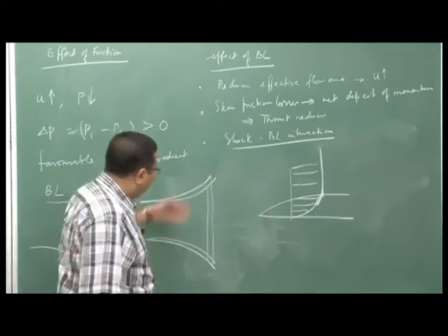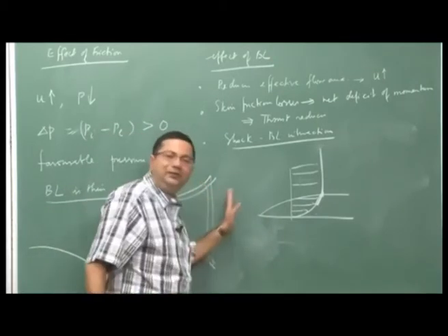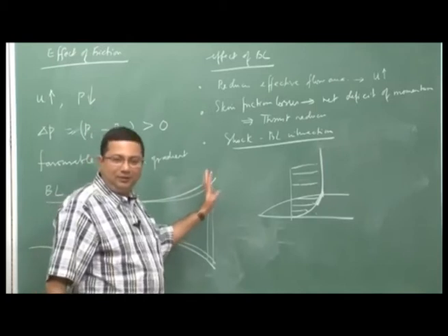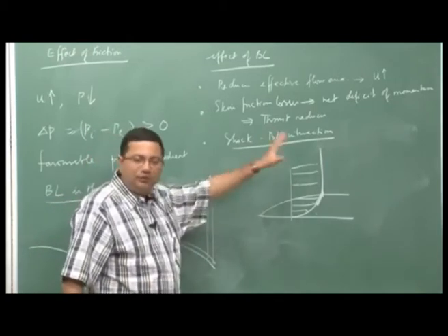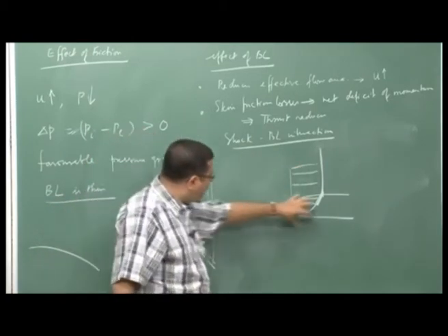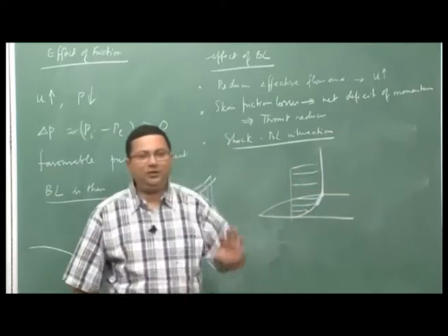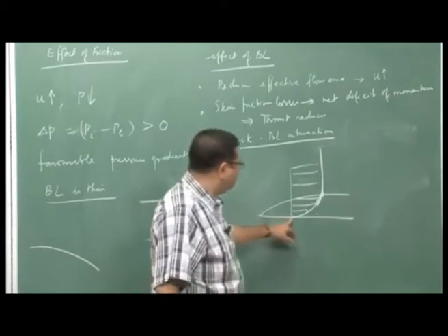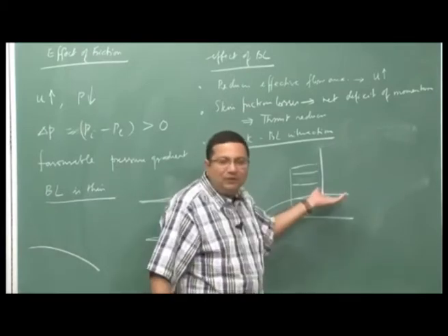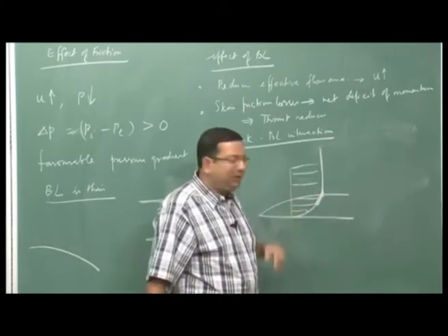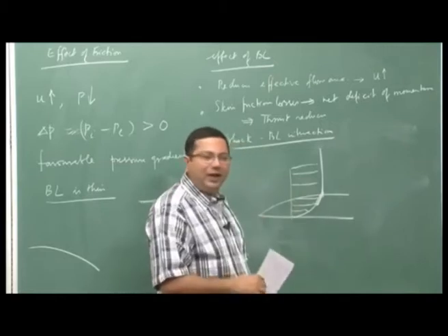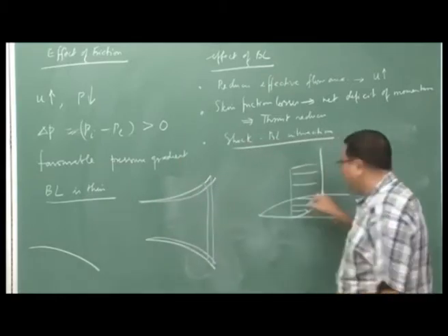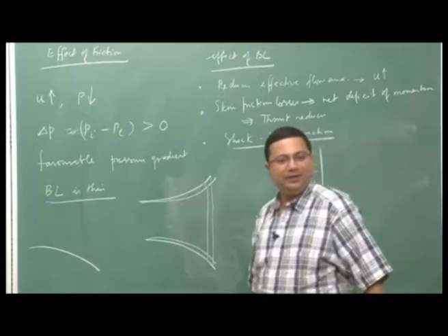So, even if there is no shock wave entering from the outside, or because of the condition of the overexpansion, there will be a shock wave close to the boundary layer, because the flow has to become subsonic before it reaches this condition, and you do not have a throat, right. So, there is going to be a shock wave here, and now this shock wave is going to interact with the boundary layer.